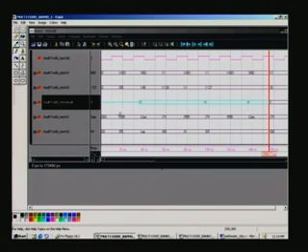In one case the lower ones are in hexadecimal, which you can easily compare with the test bench we have just seen, and the corresponding decimal can also be had by using the format option, which we have seen earlier while looking into the ModelSim tool, using which you can have the very same waveform copied here and then change the format. That is how I have got it here.